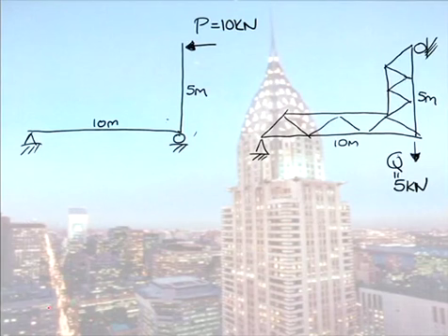So if we consider our beam system, the beam to the left here, I have a pin and a roller support, I have a horizontal load of 10 applied. So over here I would draw my two unknown reactions, and at the roller I would draw my one unknown reaction here. Let's call that A. So AY, AX. Now, just from looking at this very quickly, hopefully you can all tell me what AX equals. 10. Okay, so that reaction there is 10.